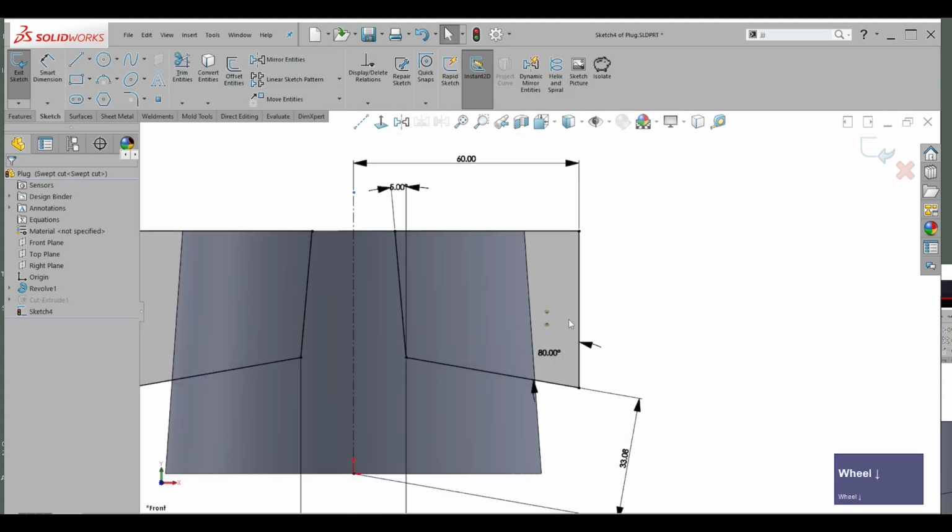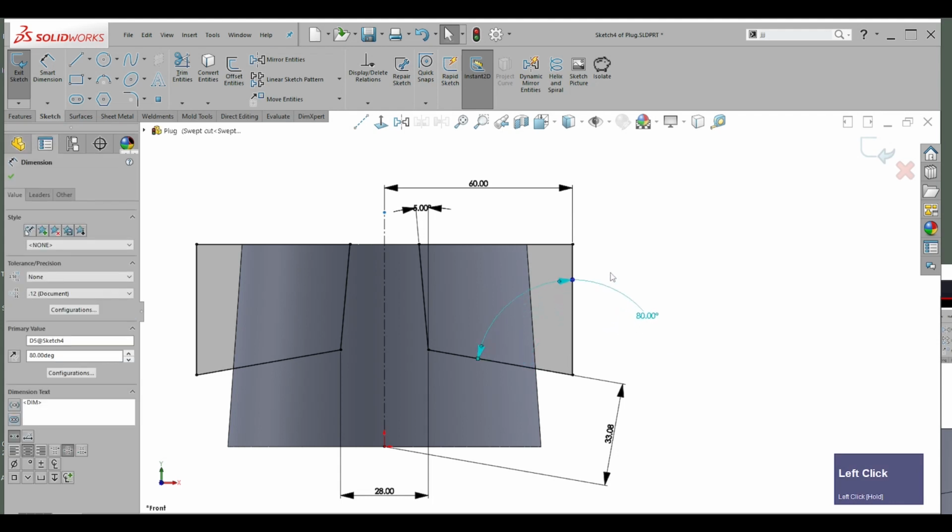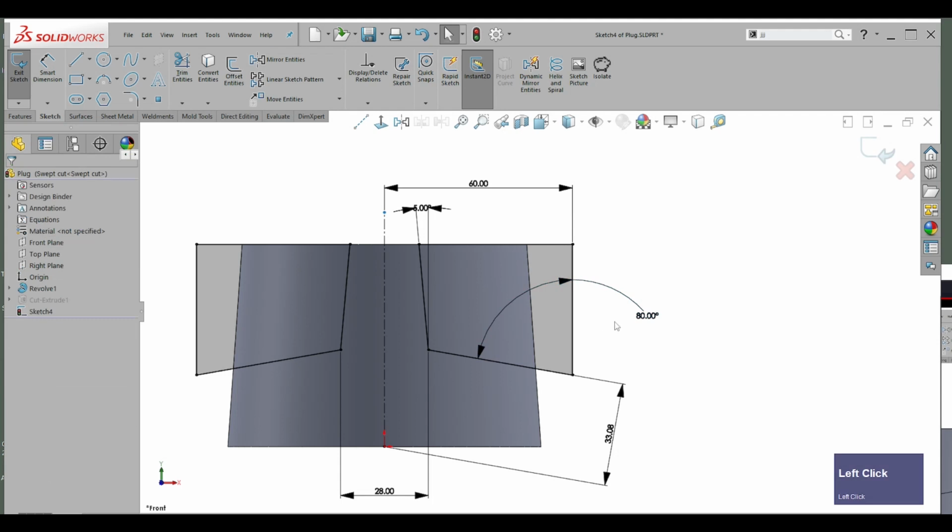it'll alter the angle. So I've pretty much got the same kind of functionality as the one where the line is just horizontal, except I've got this added feature in which if I want to change it, I can. So the point about this is that selecting your constraints and your dimensions is very flexible, and you can choose different ways of doing it to suit your purposes.